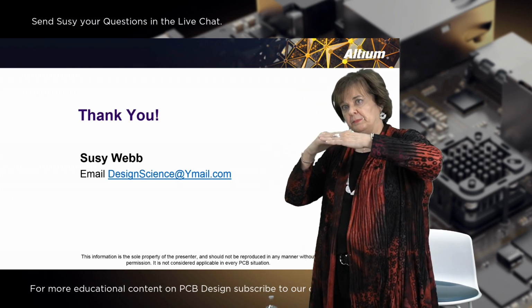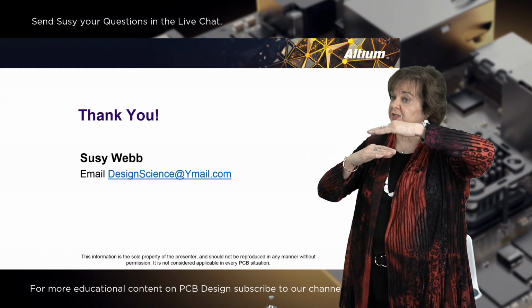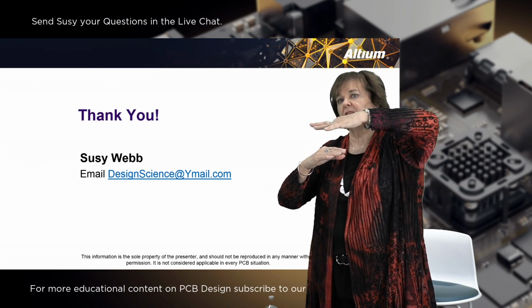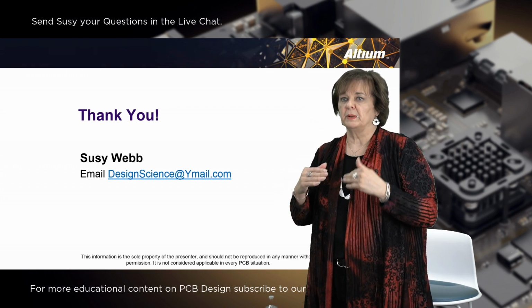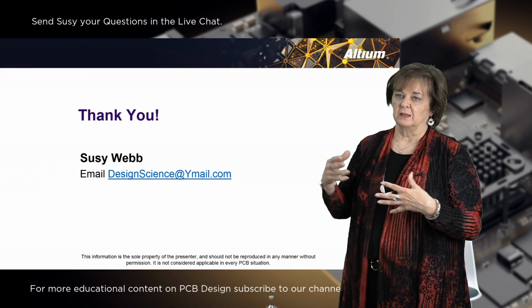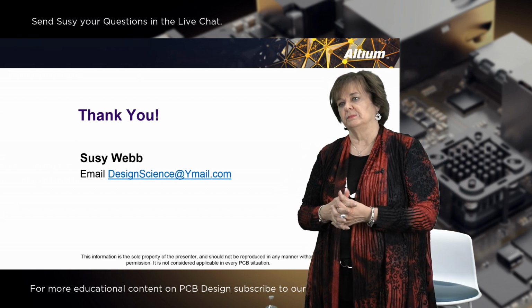And if you have a plane on either side of that signal layer, that would keep that energy even more contained. So having a plane on outer layers of both sides of the board very much keeps the energy contained within the board itself. It can still leak out. There's still high frequency energy that can get out, but it is a big help to the stack up.